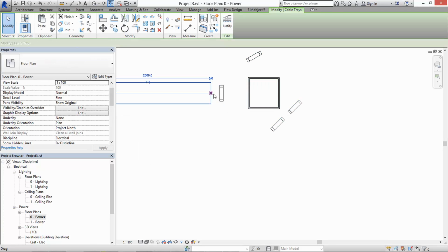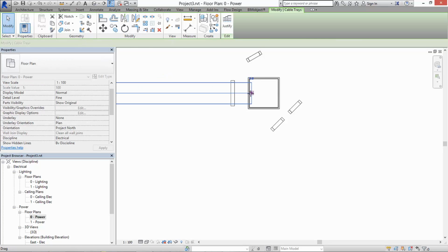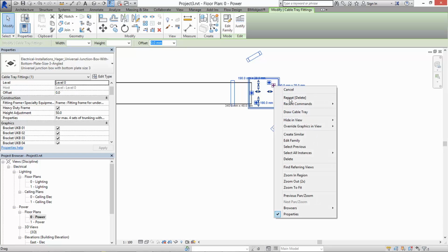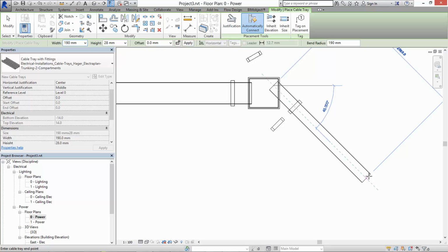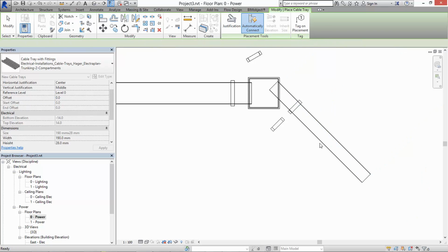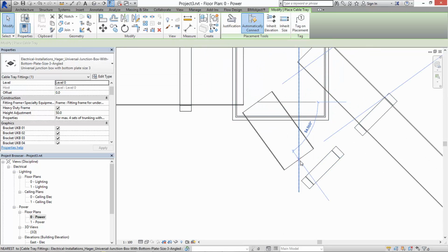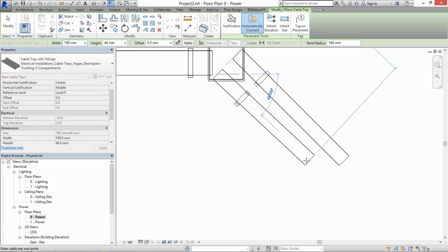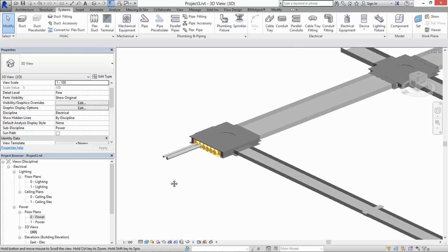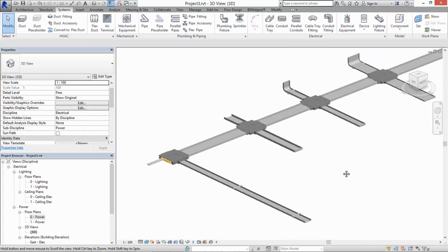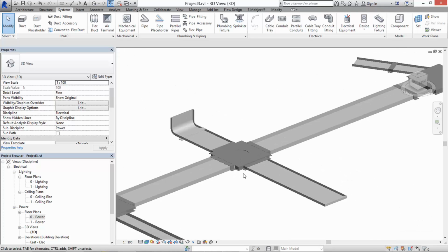As you can see here, the cable tray bracket will be automatically resized as soon as the cable tray is connected to the junction box. If you select a connector on the junction box, you can directly draw a cable tray by using the right-click Draw Cable Tray command. The junction box type Angled also includes the standard junction box, the possibility to change the fitting frames for the different floor boxes, and the installation height.